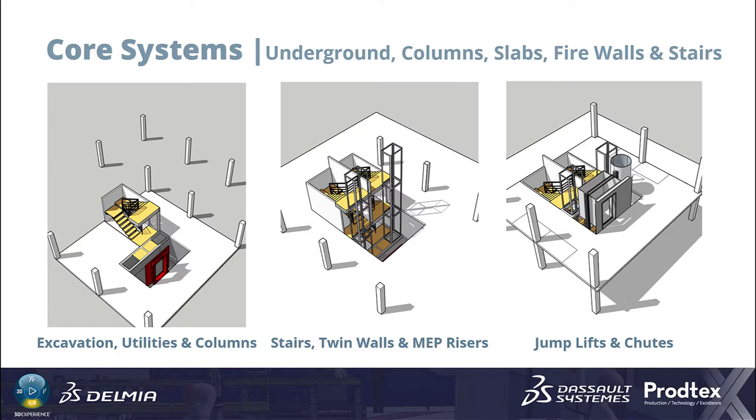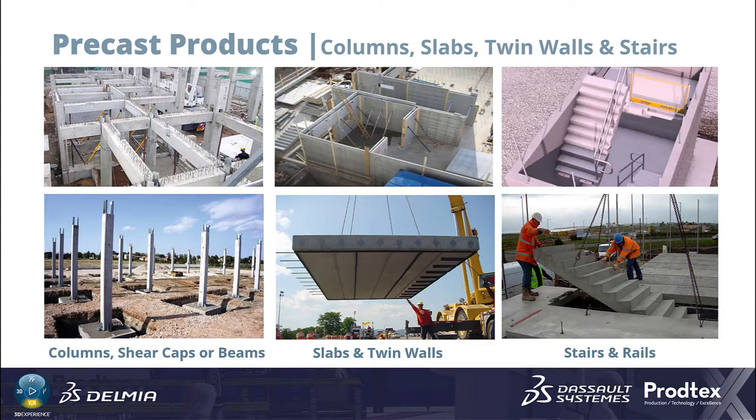The next sequence would be to add additional stairs to get to a floor above, and you'd begin to put in these mechanical, electrical, and plumbing risers. And then finally, you'd put in another level, which is just for the core only. The slab for the core gives you access to the lift, the stair, the MEP risers, and the other elements. On the ground level, there is a larger podium slab, and the units are self-supporting on top of that slab.